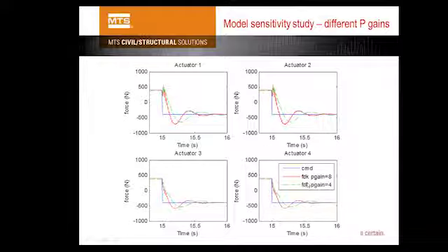But once you increase the peaking, it becomes the red one, then you reach your steady state faster, but you have more overshoot. That's just a more aggressive peaking. For example, once you have a more aggressive peaking, especially on those actuator 1 and 2, you can see that this feedback started becoming marginally unstable. You can see those very high frequency chirping signals in there, and it doesn't damp out over a long time. That means peaking of 8 is probably already too aggressive.